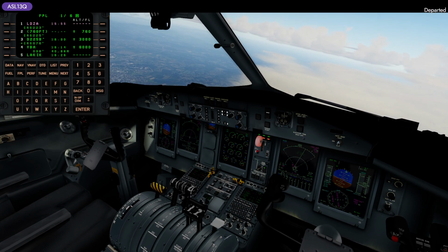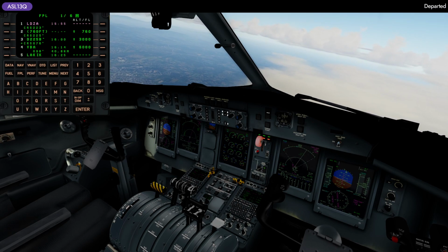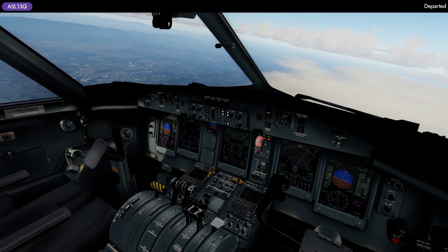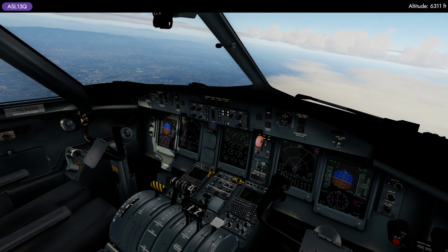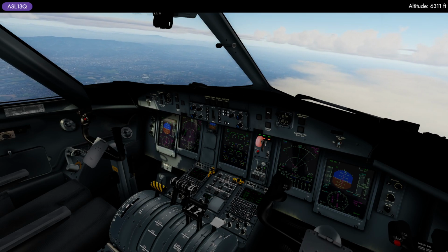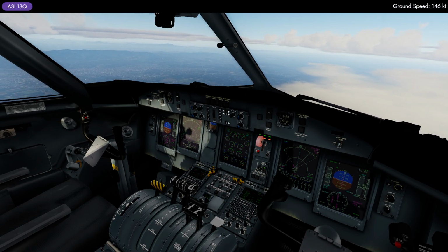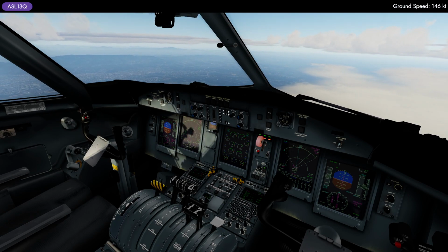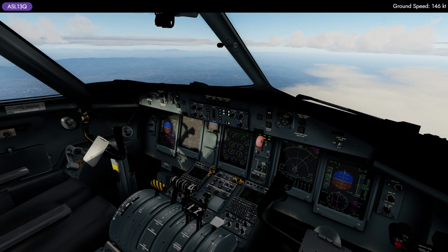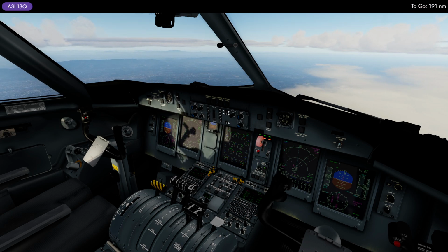Our flight plan for that. But we don't actually need a flight plan for that. What I need is to stay parallel with it. So if it was 220, it will be 043. Parallel course to the runway.